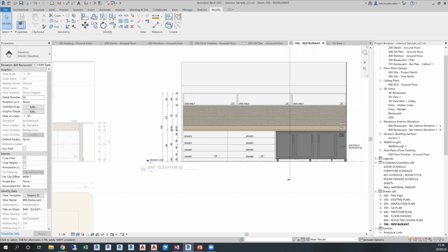When walls are drawn in Revit on the 2D linked AutoCAD file, if the 2D file is updated in AutoCAD, do the walls in Revit move too? No, they don't. They are still two separate drawings. The link with AutoCAD creates an underlay that you can use to start your work, but it won't get updated automatically.